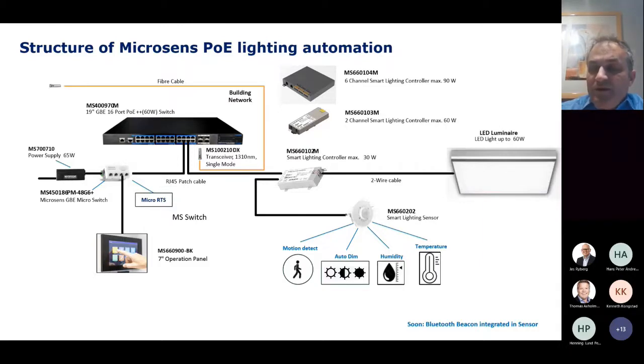You can configure them individually during the commissioning of the device. This task is called calibration in our world, and with the calibration you define the maximum output you have to deliver to the connected LED device, and you can connect up to 6 of those devices independently.